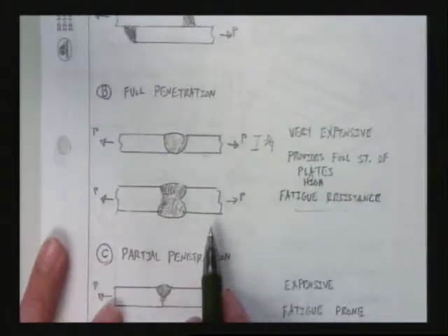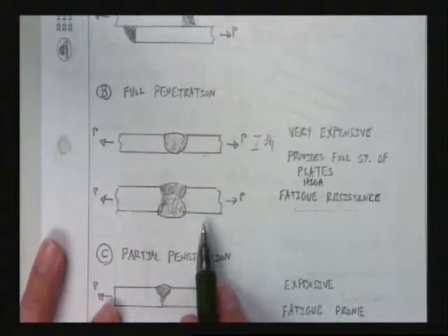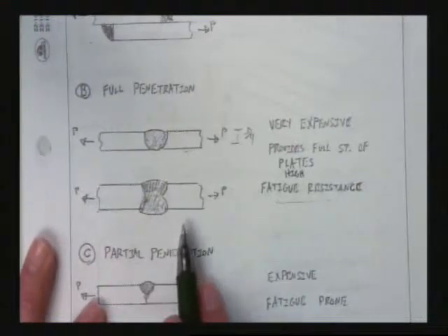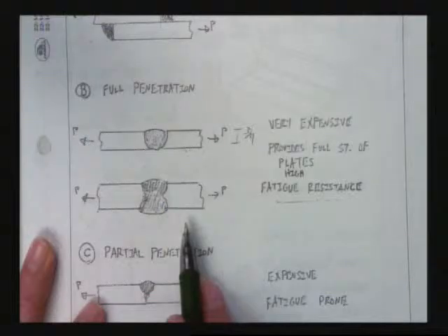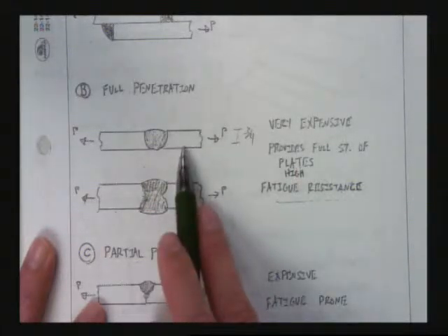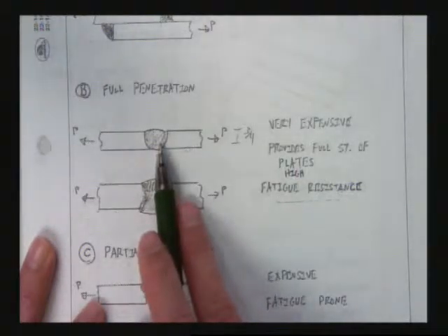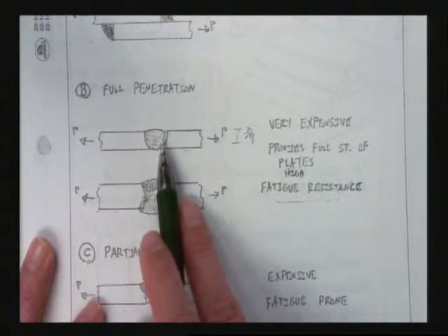There's different types of welds, fillet welds, which we'll be talking a lot about today, and full penetration welds. The coolest thing about the full penetration weld is that you don't have to design it. You just specify it. Okay? If you specify a full penetration weld and they know what the base metal is, they will use an electrode that will provide enough strength so that the load can be transferred. Now there's a lot of labor that goes into full penetration welds, and you should avoid them if you possibly can.